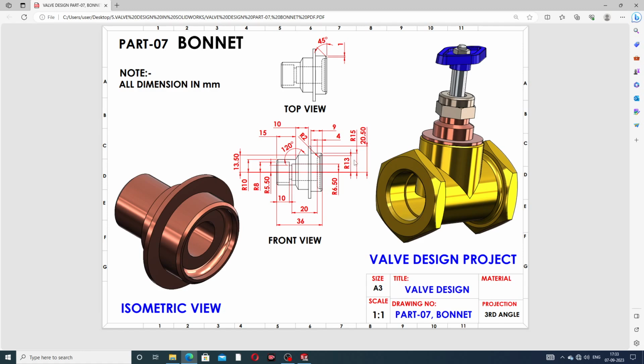Then all geometry of the half part is drawn here. Then this axis of revolution is drawn here, and this length is 20.5 millimeter, and this is 15 millimeter, and this is 13 millimeter, and this is 6.5 millimeter. Okay, one by one is drawn here.